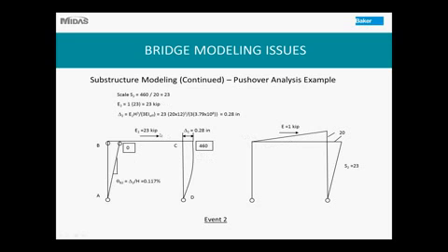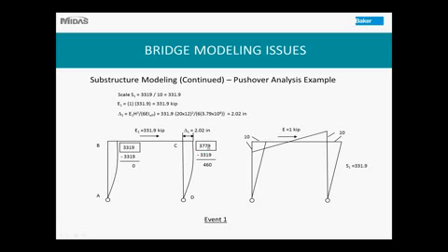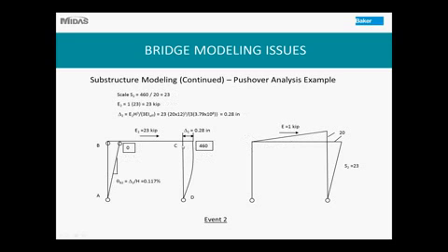At event 2, the joint at the top of column at point B has already reached the plastic moment. So there's going to be a plastic hinge here, and you have only one column which is able to resist the lateral loads. And remember, on event 1, you already took away 3319 kPa from 3779 kPa. You're left with 460 kPa here. So the reserve capacity at point C is 460 kPa.